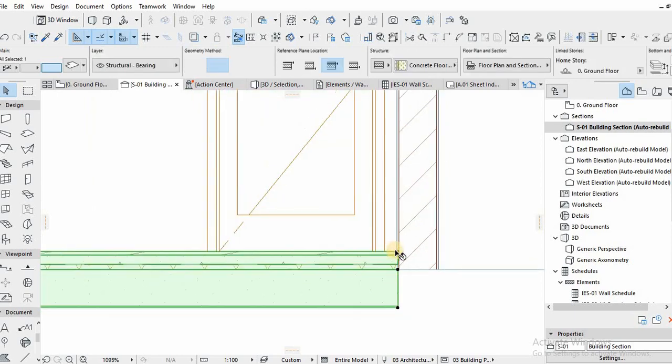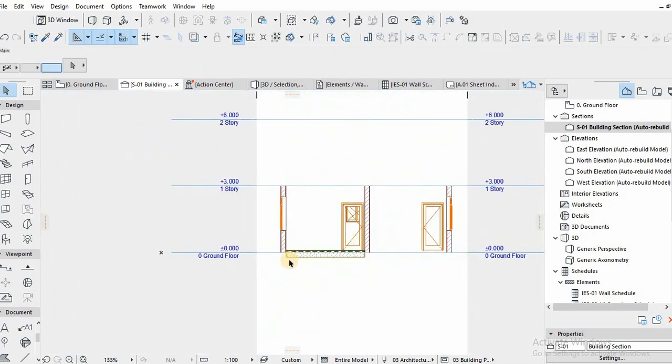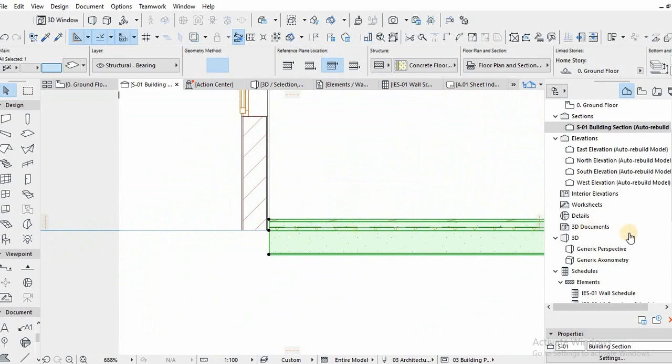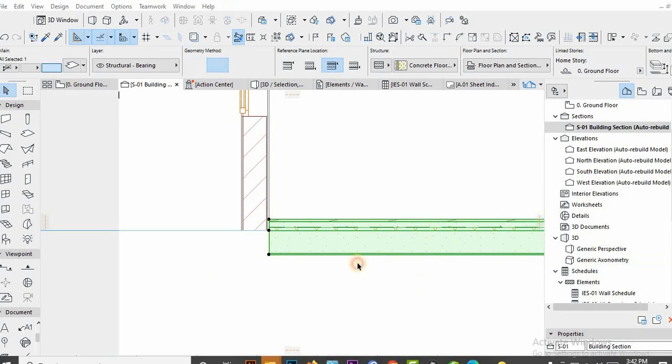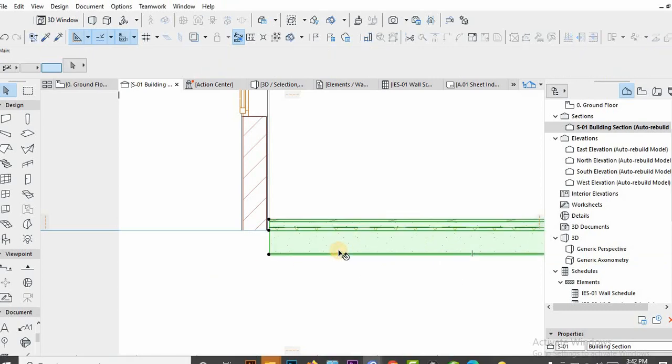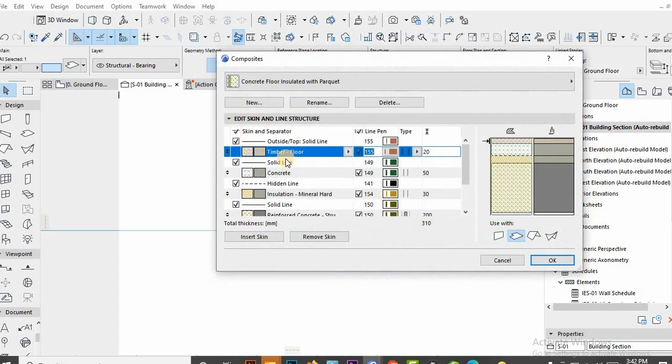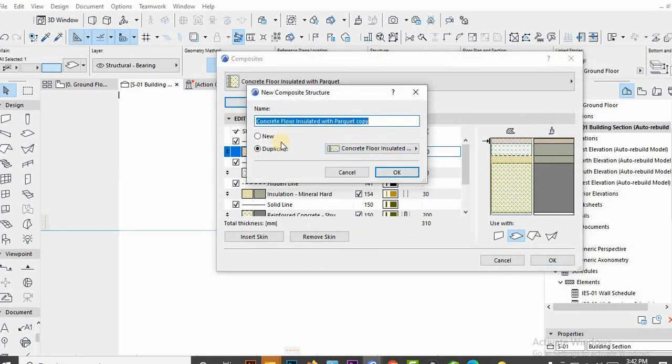We're going to model everything from cornices, ceilings, and trusses, and here now we work in compositions. Depending on your standard, on how you design wherever you are, you could play around with this composition. So I'm going to edit mine. Slab 100mm thick, I need, yes. So I'm going to choose a tile.